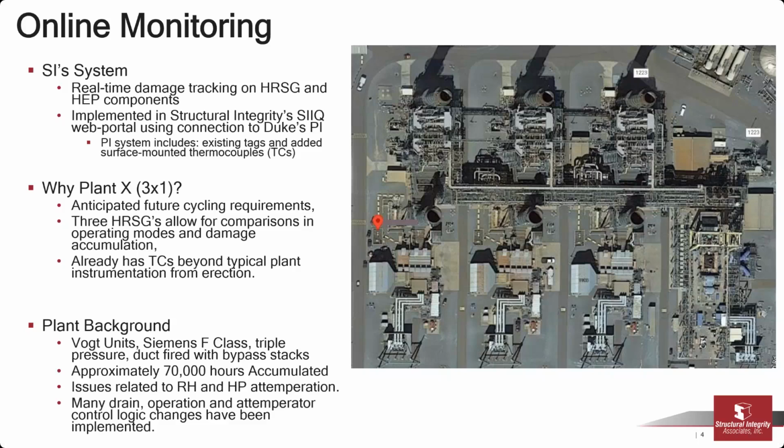Of course, as part of this, we had to collect all that historical operational data to give to SI so they could go all the way back to commercial operation to start analyzing these components. This site is currently in base load and load following operations, so not a lot of cycling yet, but we do anticipate in the future that because of renewable load growth and changes in our loads, the combined cycles are going to have to start cycling more often. That's really where this program will show a lot of value, because of all the wear and tear that the components will take as we start to cycle these units more.